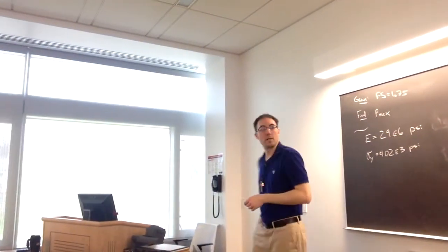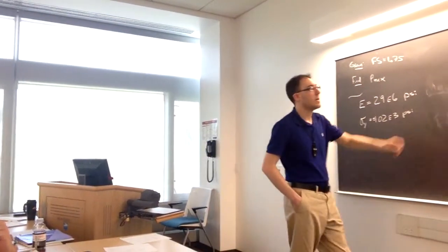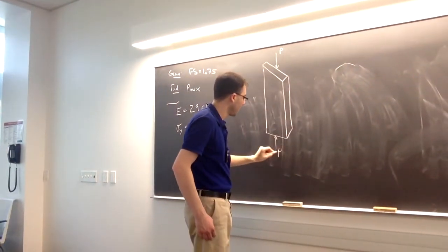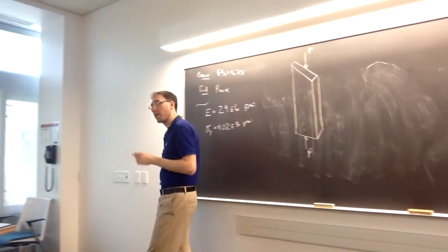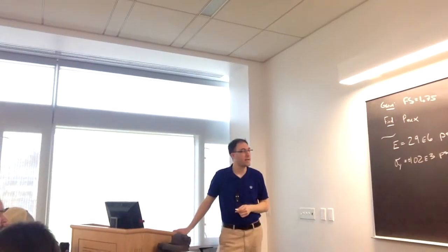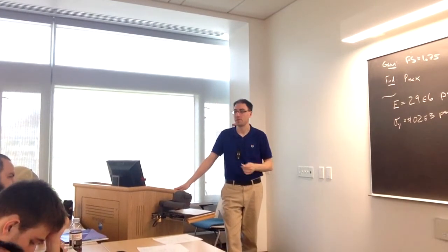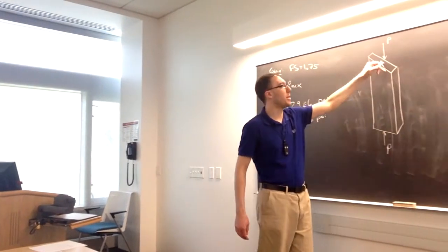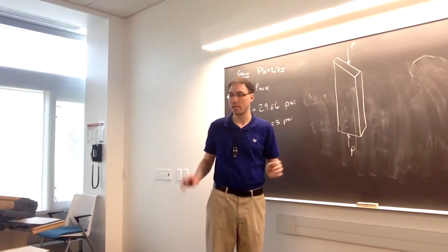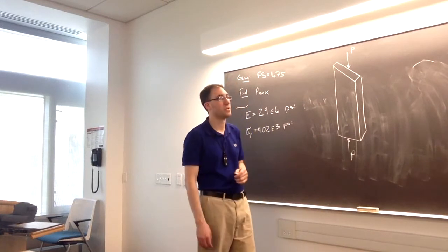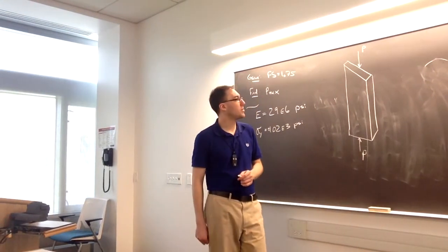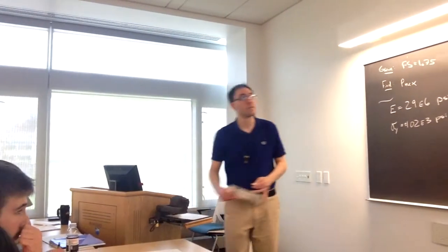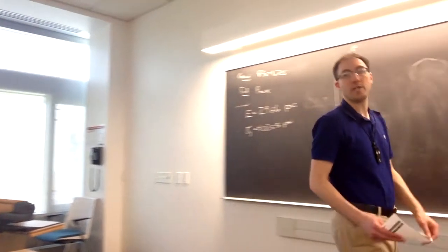So if I isolate our link here, we're applying, again, this value of P on top, this value of P on the bottom. And for the Euler buckling, we're only looking at cases where we only have an internal normal force. We don't have a shear or a bending moment or anything like that. And these are being applied through the centroid. Those are always going to be the assumptions we have to make to use these equations. So we want to align this in the proper dimensions with how it's being applied in this situation. Right, so the nominal length is 24 inches.